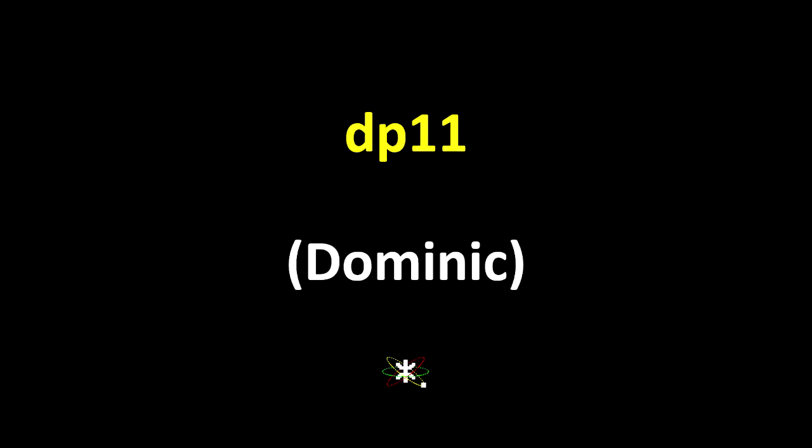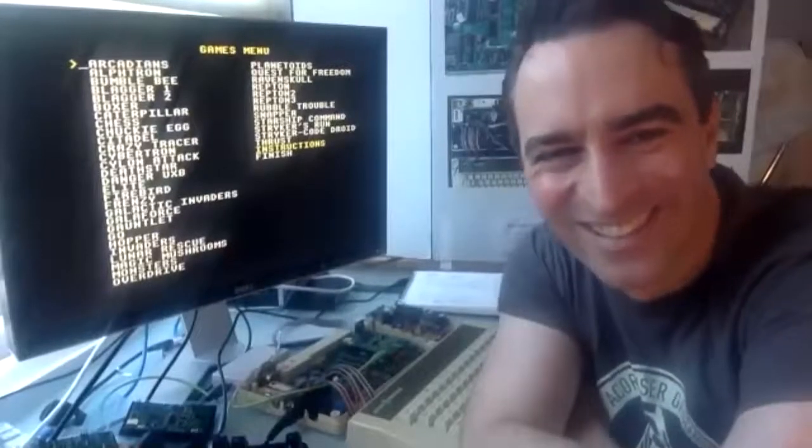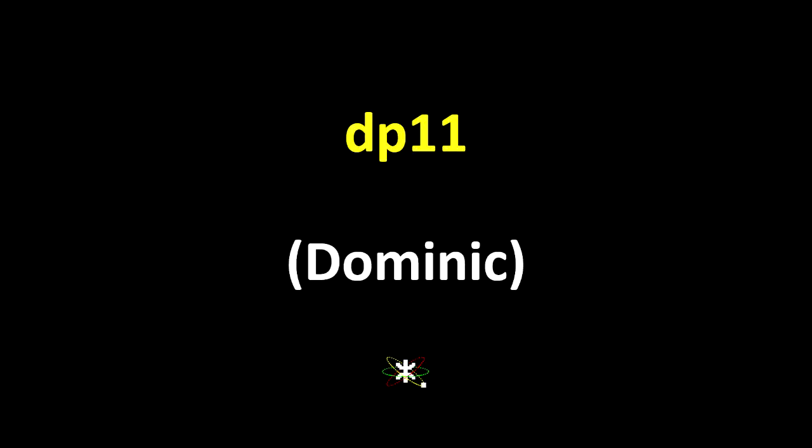Back in the 90s, with a bit of trickery, with 2 resistors and a capacitor, I was able to get composite video into an FPGA, and then another 2 resistors and a capacitor to get it back out again. That's amazing. It wasn't the world's greatest composite video source, but it was good enough that you could get composite video across.